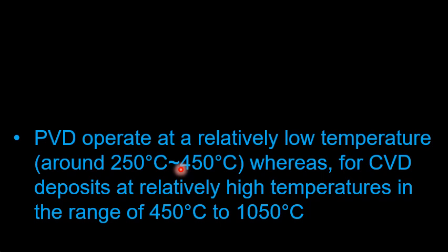You just need operating systems like electron beam or pulse laser, or thermionic type of filaments. So basically they heat a small region of the precursor, the source material, which has a very high temperature, but they are connected with a cooling system. So overall the temperature of the reaction chamber during a physical vapor deposition process is less.